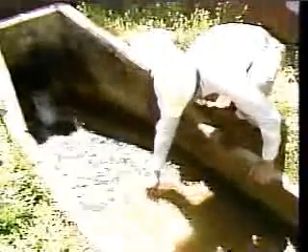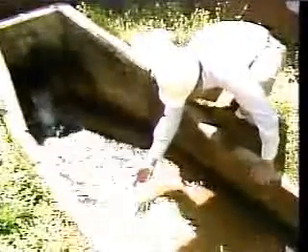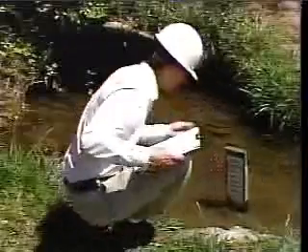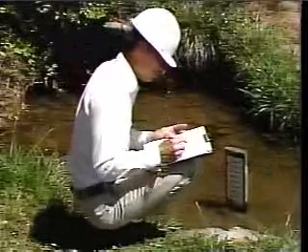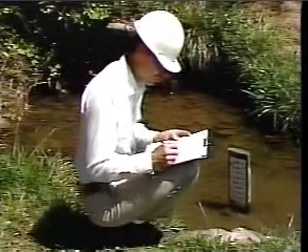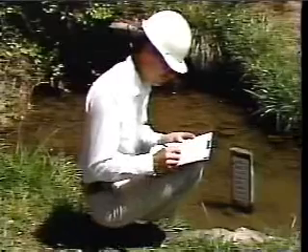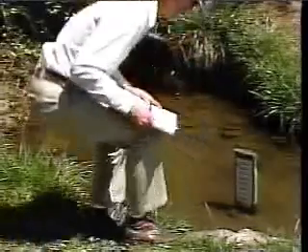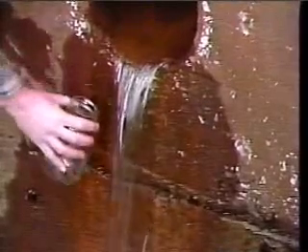When you encounter sediment buildup in the weir box, try to determine the cause. Sediment is usually from runoff erosion. It could also be an indication that piping is occurring. This is an example of how you always must carefully consider the reason for everything you see as you carry out your inspection. One last thing you want to pay attention to regarding seepage is its clarity.